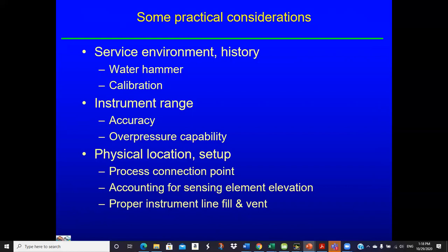A smaller company, if you want to know, you better take your own gauge. And hopefully you've got a handle so you can close it off, take their gauge out and put your gauge in. Then you have some confidence in the reading, because any of this data, if you don't have some real reason to think the gauges are good, you have to take with a grain of salt.